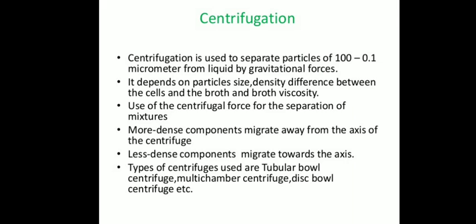Now here the gravitational force is applied on the liquids so that the solid matter will get easily separated. It depends on the particle size, the density difference between the cells and the broth viscosity, meaning the separation of your product and the other matter. It completely depends on the size of the particle, as well as the density difference between the cells and the broth viscosity.